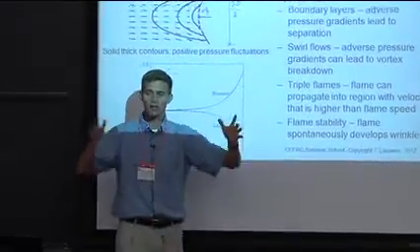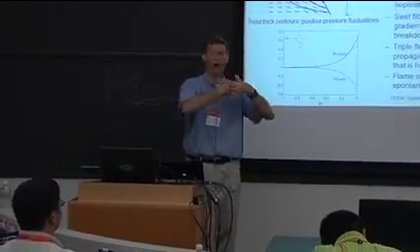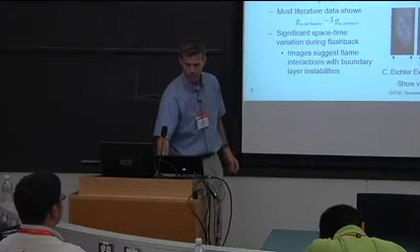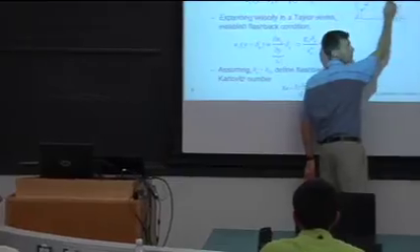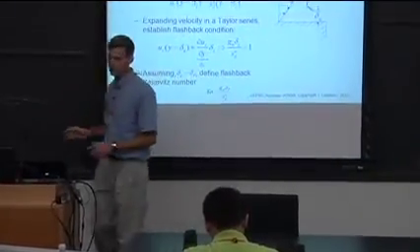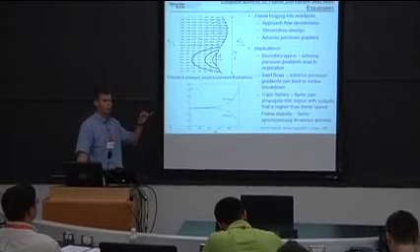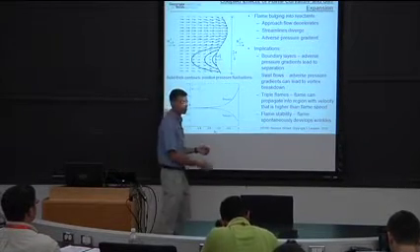like this, because by geometric necessity, the farthest forward part of a flame has got to be positively curved. It's got to be curved into the reactants, right? Like I've drawn here. The farthest forward part of a flame's got to look like that. So I've got a special interest in positively curved flames. And so what do we know? Positively curved flames impose an adverse pressure gradient. They decelerate the flow.